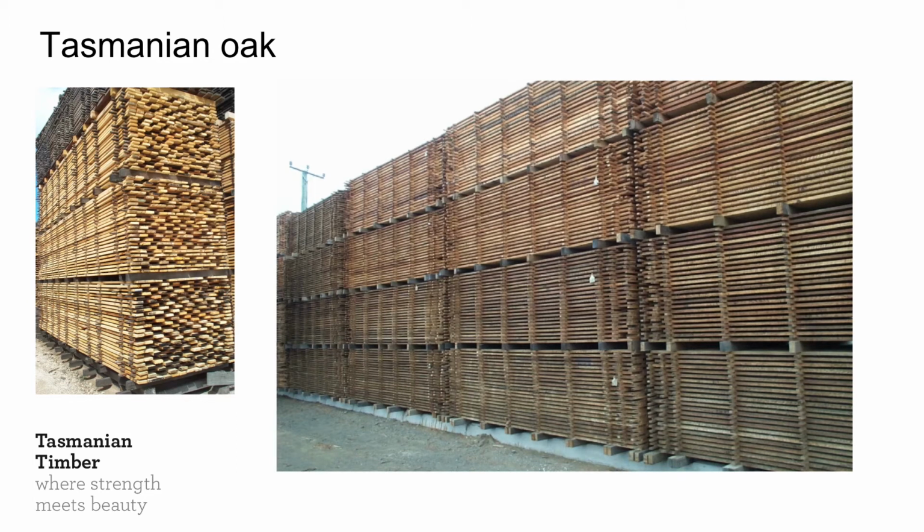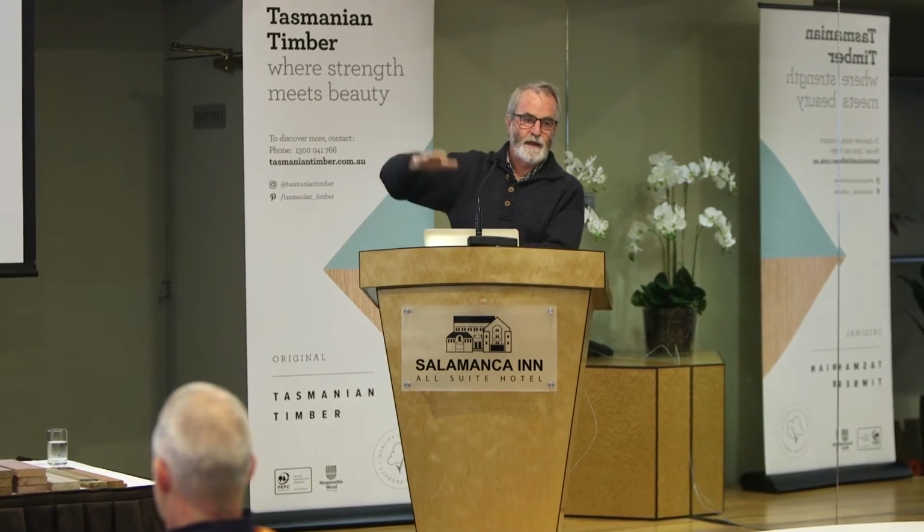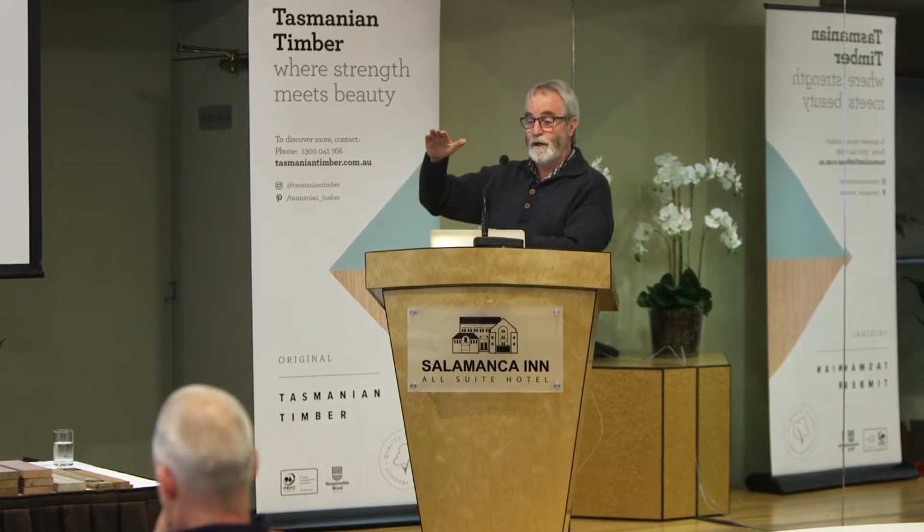I will talk quite a bit more about drying later on, and moisture content control. One thing I will say is that when they stack these up, there might be a particular height to all of the stacks put together, and as it dries, the stack will shrink. So it might be half a metre lower at the end than when it goes out, because as the stuff dries, it does two things in Tasmania. One, it shrinks, and the other, it collapses. There's a thing called collapse. And then you steam it up and it pops back up again. But it shrinks quite a deal.